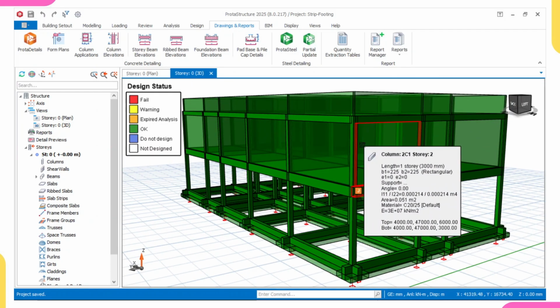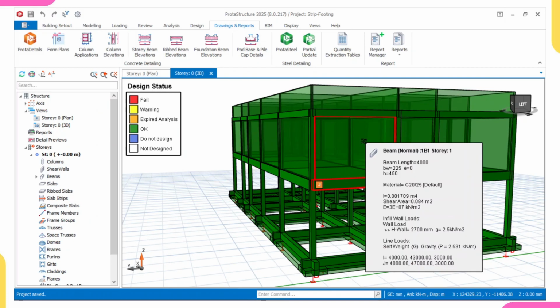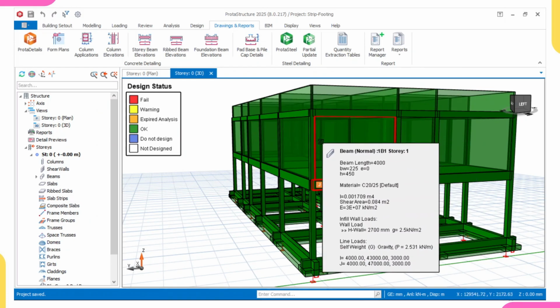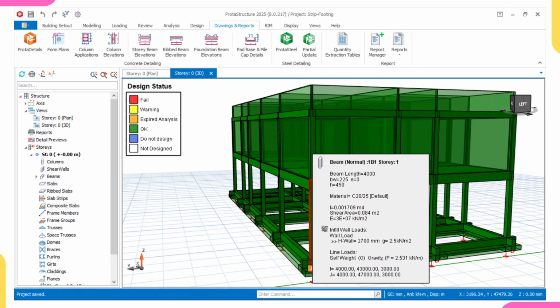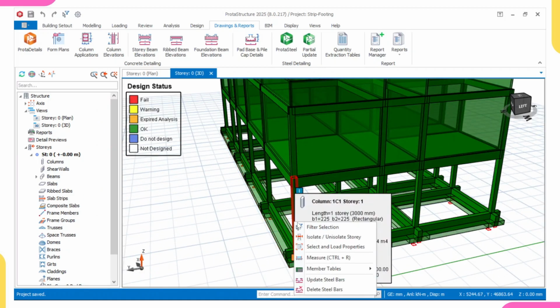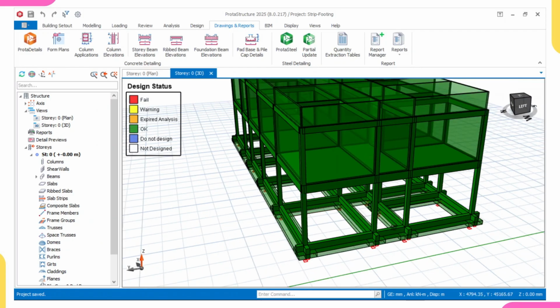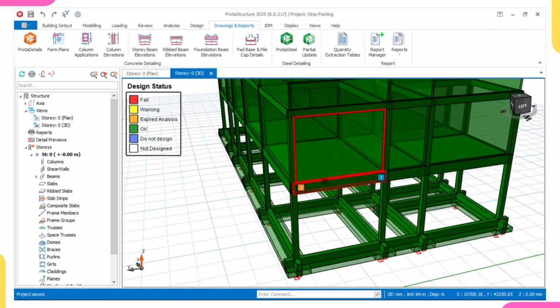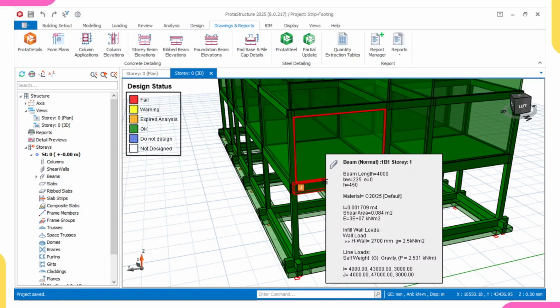Okay, let me tell you. To group your columns, there are 7 criteria or conditions that your columns must meet before you group them as one. First is that they must have the same length. All my columns start from the ground floor to the roof level, meaning they all have the same length. If one started from the ground floor and stopped at the first floor, it will be another type of column because they don't have the same length.